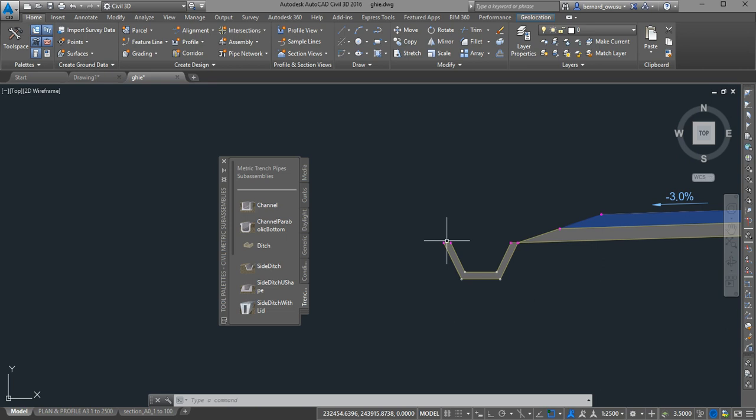Okay, whatever. But you may have, let's say, your backfill, you may have a side slope. You may want to slope it, either if it's in a cut, or how we should behave if it's in a fill. If it's in a cut, then you have a slope this way. If it's in a fill, this will be down there, because it's in a fill. It will not be collecting something from down to top. So we are going to put what we call the daylight.